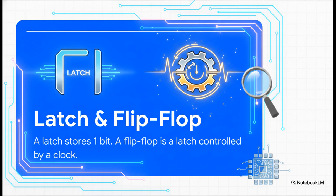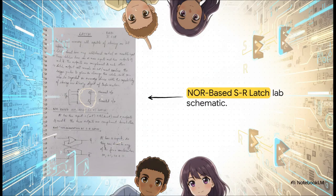A latch is just a basic memory cell. It's capable of storing exactly one bit of binary information, and importantly, it does this without a clock. A flip-flop, on the other hand, is essentially just a latch, but upgraded. It includes additional control inputs, typically driven by a master clock, which strictly dictates exactly when the circuit is allowed to change states.